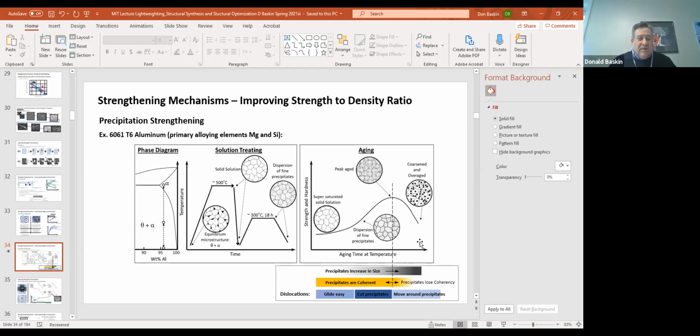And so I had to go in there and say, okay, guys, let's do some experiments and figure out how long this motor housing can really sit in there before we start having a degradation in strength. We left the motor housing in the furnace for 5 minutes, 10 minutes, 20 minutes, 30 minutes, 40 minutes, and took hardness tests to figure out when the material was beginning to soften. It turned out that it was really only good in there for about 12 minutes before it would start softening. So they cleaned up their act. They put controls in place so these things would never stay in the furnace more than 12 minutes.